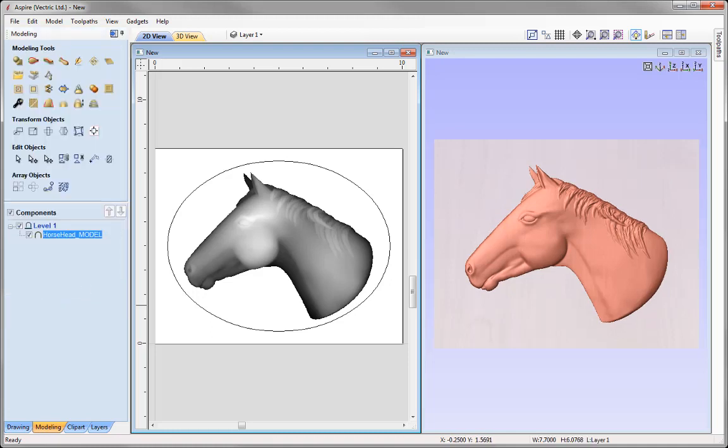When we create parts that are going to be recessed or dished below the modelling plane, then it's important that we have a component that represents that plane for the dished or recessed shape to merge with. And there's two reasons for this. One, it helps us to visualise the part, and two, it helps us to prevent some possible issues that we may have when it comes to machining, where it allows the software to better define the exact point where the recess or the dish shape meets with the surface of the material, which will ultimately result in a cleaner toolpath with a smooth machined surface.